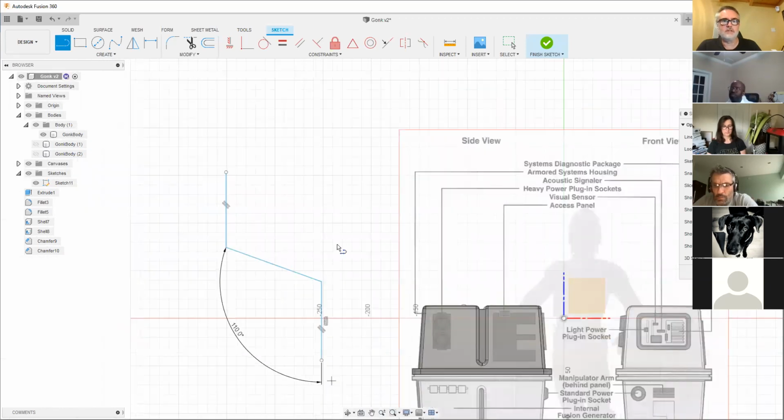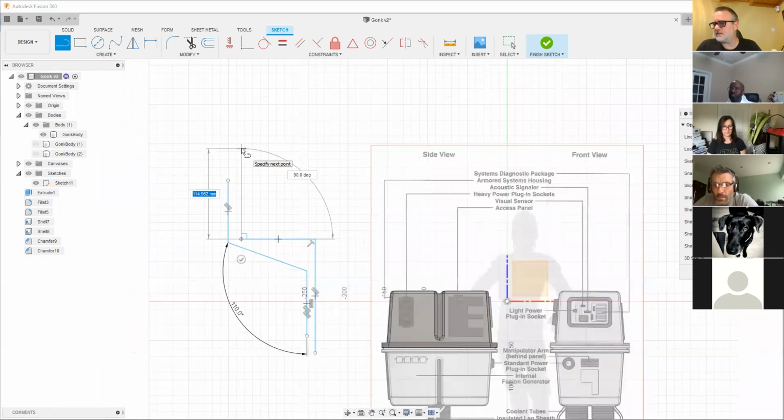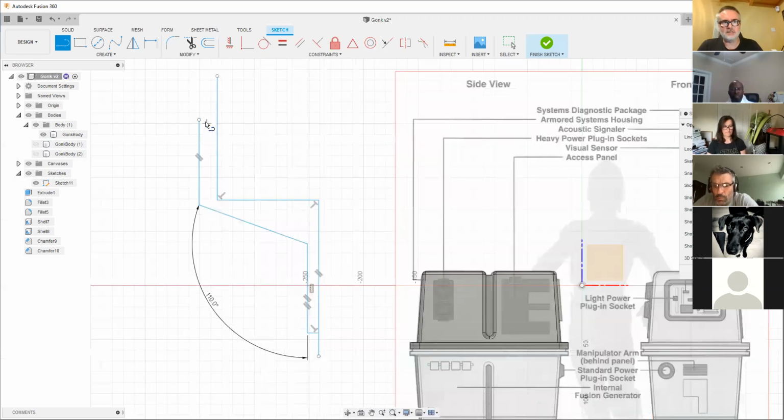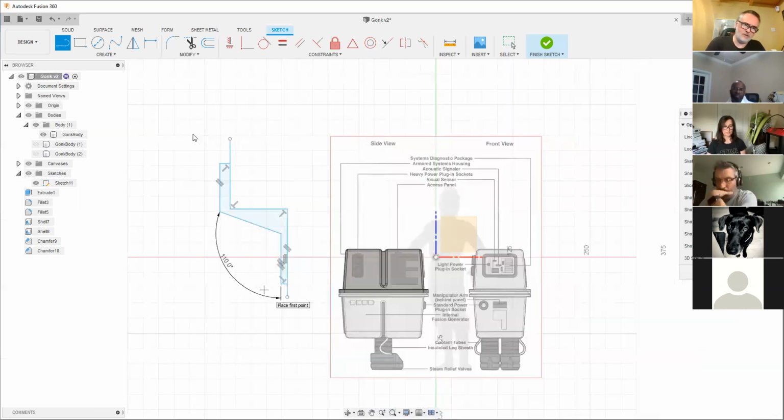I did this for the little bread pans in R2D2, where the model comes out and you've got this flat bit, and then obviously that's where the bread pan is, the hole. So by using a 20-degree angle on that, I can still print that. It doesn't matter if it's a bit rough on the inside, it just means it's printing without any support. So if you've got it at the back of your mind that you're going to print these things, and you do that little bit of problem solving as you go through, it can save you trouble later.